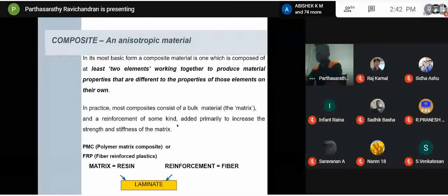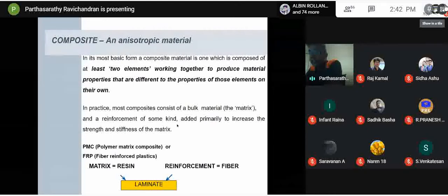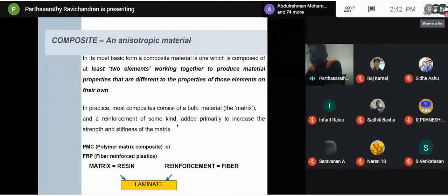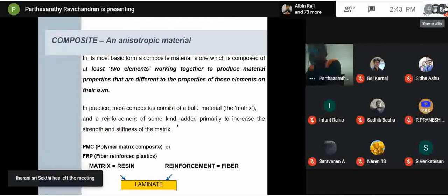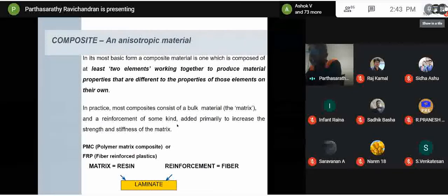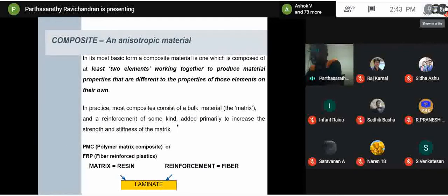As far as the nacelle cover is concerned, there is no hard and fast rule to put it in 45-degree or any other degree, but usually they would go with 0 and 90-degree bidirectional mats, which you can find readily available with most of the suppliers, and that's what is preferred. I've not found any papers which say that you have to use a specific direction unless the load keeps changing.